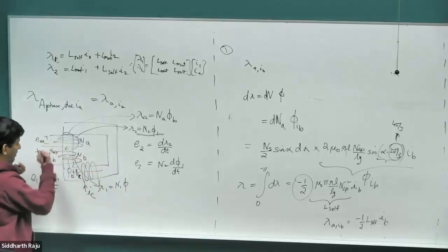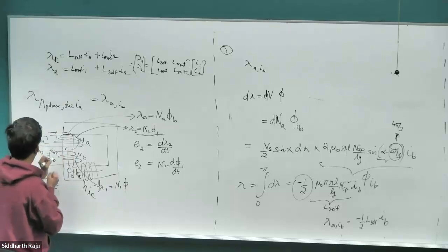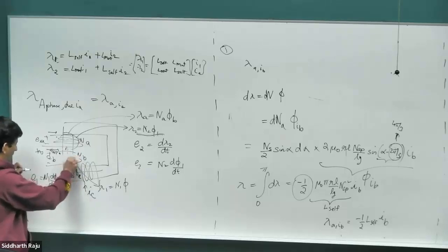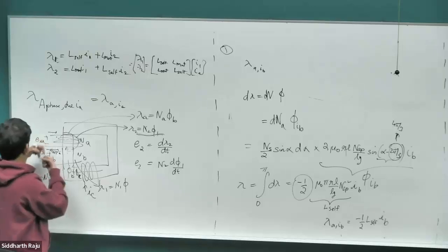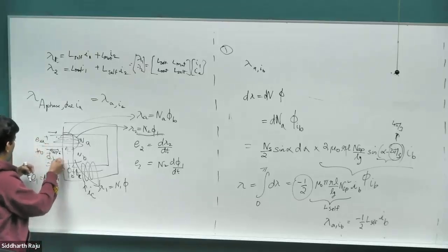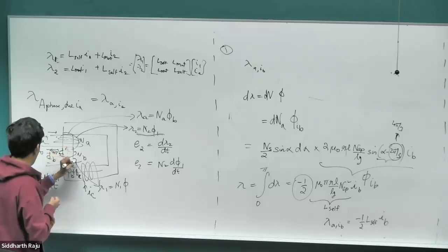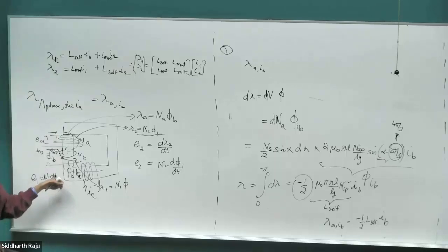So instead of winding it like this, if I wound it the other way around, right? Because I want the currents, let's say in this case, current going into the dot, current going into the dot. So the answer both Jack gave and Hannah gave are exactly one and the same. Either you can reverse the current, call this the dot and current going into this, or reverse the coil. Right? So now the current going in will create a flux in the downward direction.